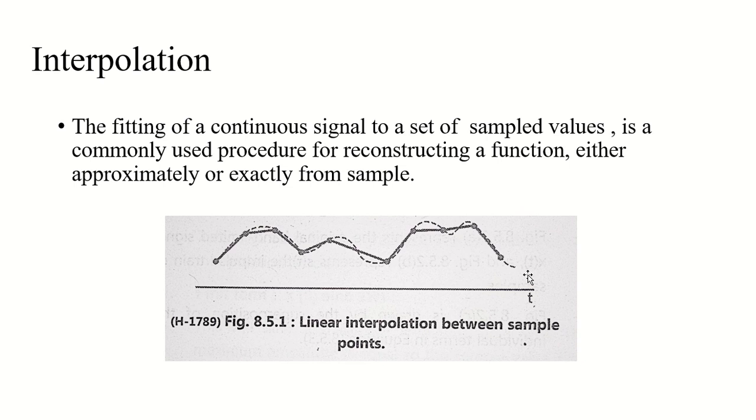So we have already seen in the previous section that for band limited signals, if the sampling instants are sufficiently close, then the signal can be reconstructed exactly by using only the low pass filter, and we can carry out this exact interpolation between the samples using this. So the reconstruction of my original signal, let's say x(t), is a process of interpolation that makes it clear. And when we consider the effect in the time domain of my ideal low pass filter, we can find the output of the low pass filter, right?